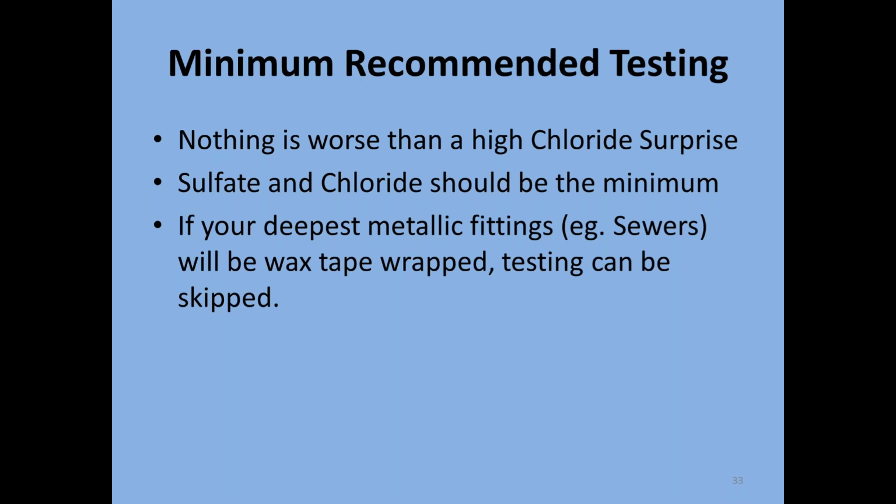Like I said, one of the biggest surprises that people get on many sites is not knowing that there are high chlorides in the site. And that's because everyone was simply testing for sulfate, because that's what the building code requires. But like I said, sulfates are just for concrete integrity. So at a minimum, I recommend you test for sulfate and chloride.